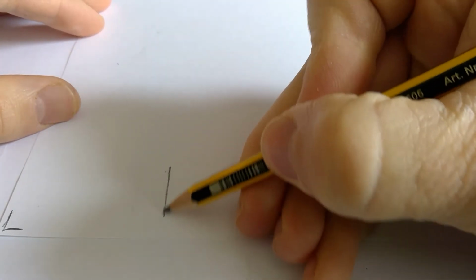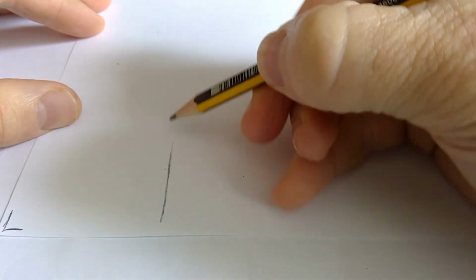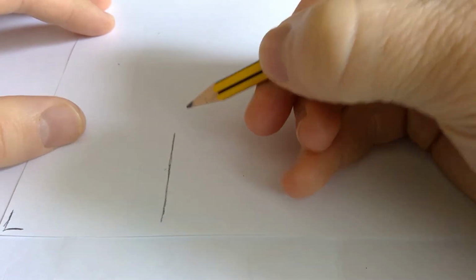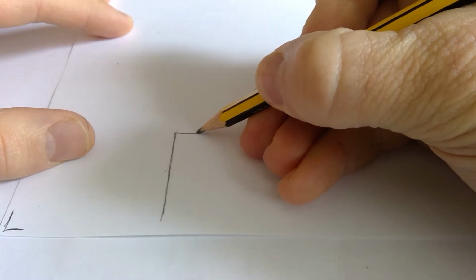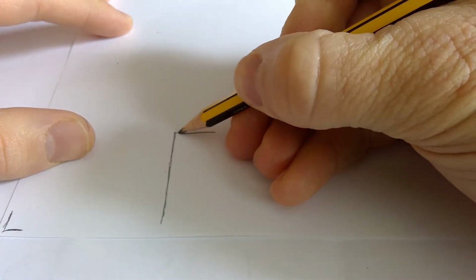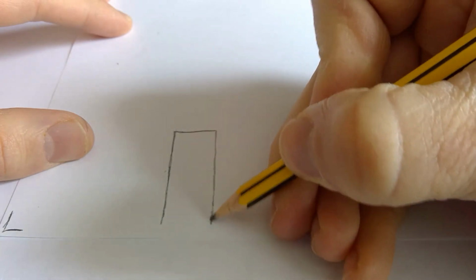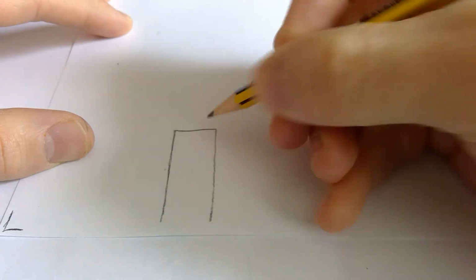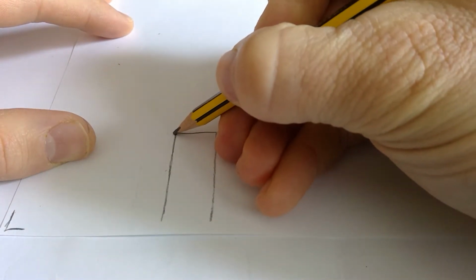So timber frame panel, it's said to go 400 millimeters below, so make sure you go up 400 millimeters. When scaled down by 1 to 10, that will be 100. So leave yourself 100 millimeters of space there. The width of the timber frame panel, it's said, is 200, so make sure you make that 200. On the inside of a timber frame panel, we have a service cavity here, so we're going to leave that for the moment.